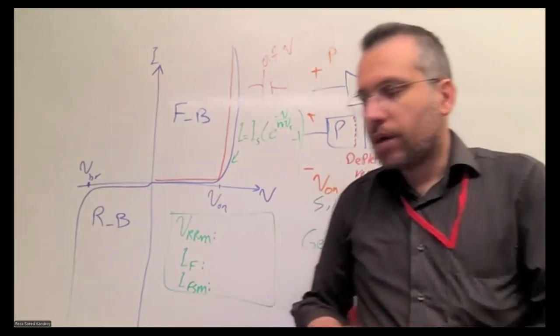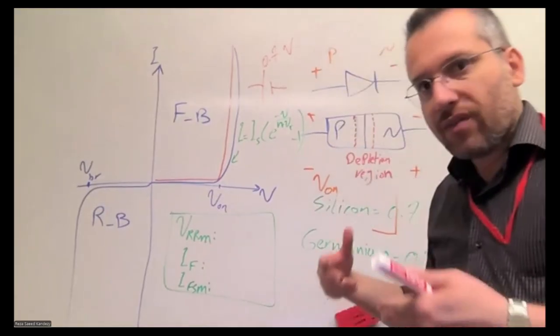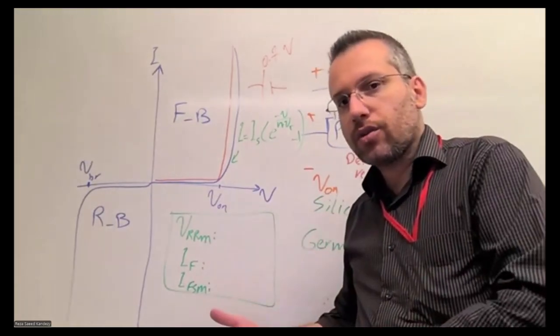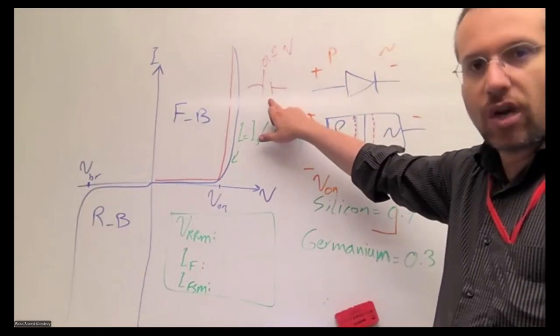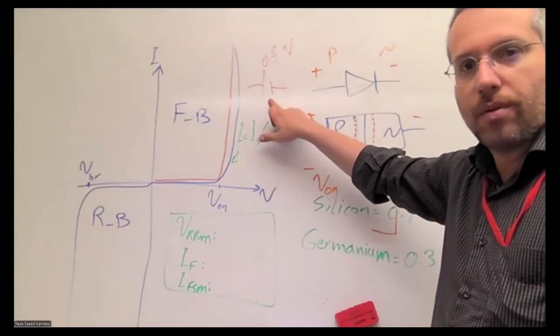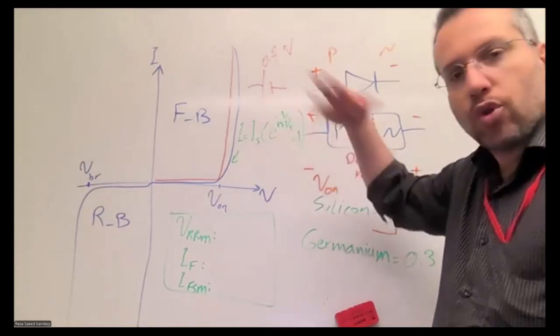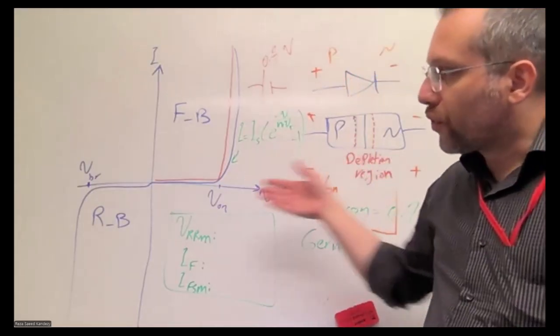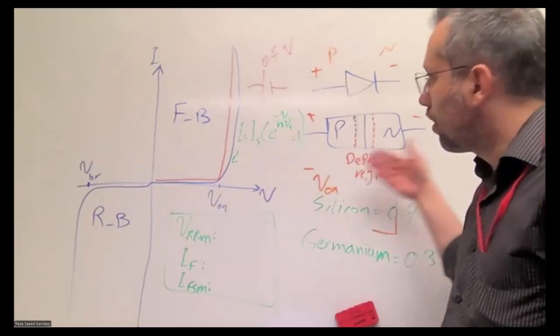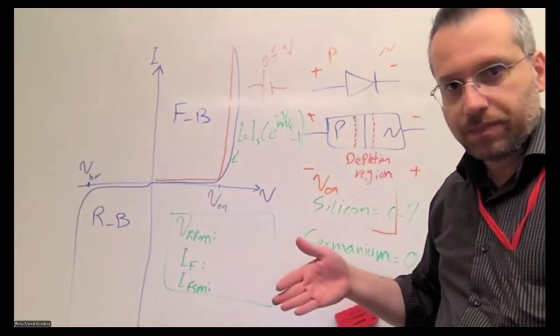So in forward bias, if you have a diode in your circuit, just replace it with a DC voltage drop, and you're good to go with the analysis. If it's in reverse bias, that means there is no current, so it's an open circuit.